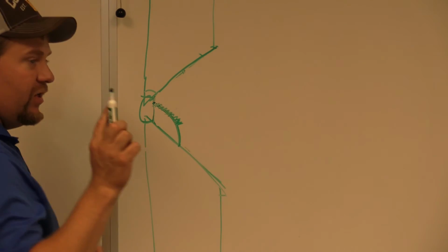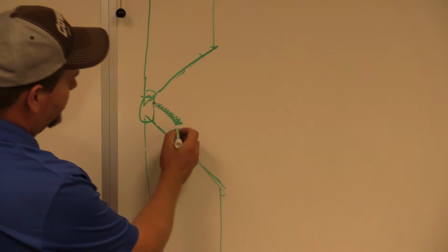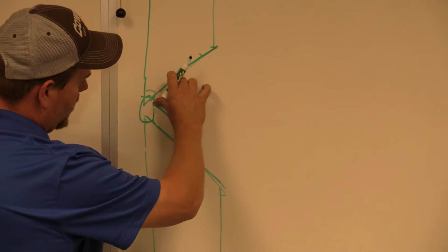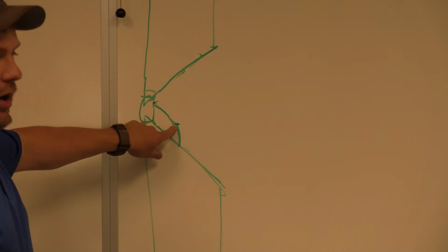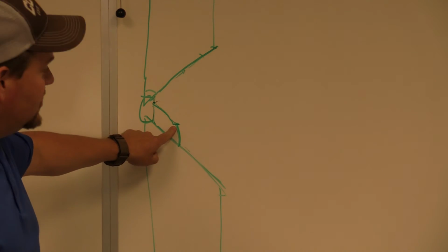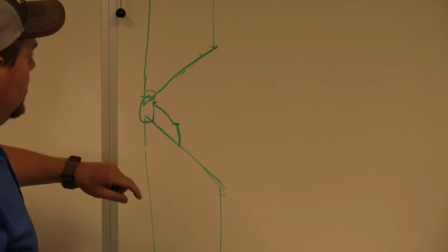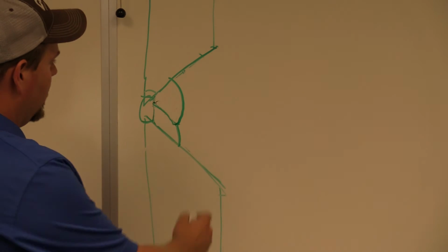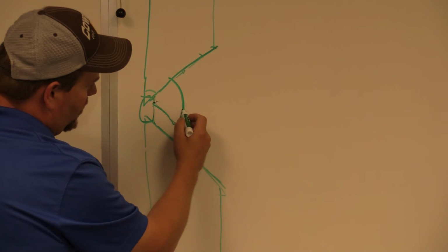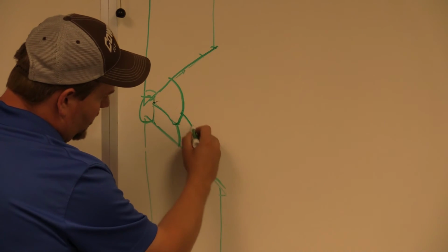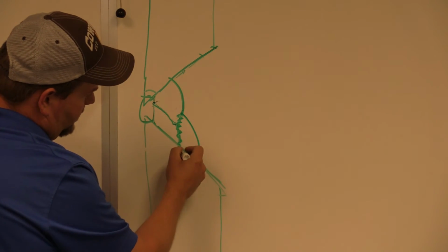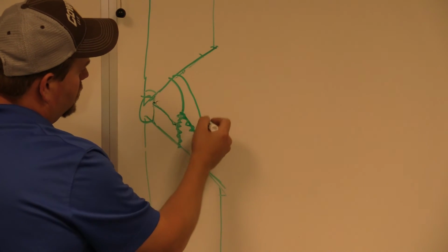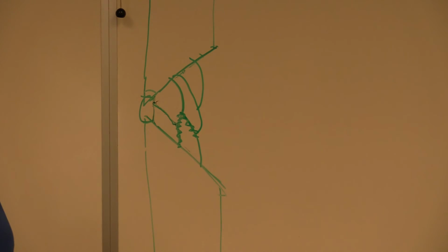And how this helps me at the same time is if I put a groove right here with my grinder, then this is also going to give me a target to shoot for when I'm welding. So that's going to tell me where my high point is. Then I'm going to weld from here to here. Now I can come back and I don't have to grind the whole thing at once. So I'm going to do the same thing here to here: grind down from here to here, weld that. Same thing, grind. See what I mean? Okay.